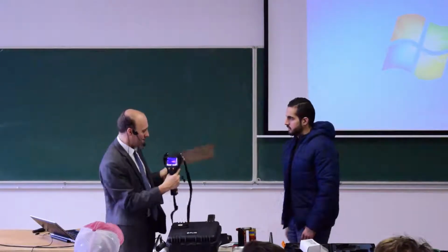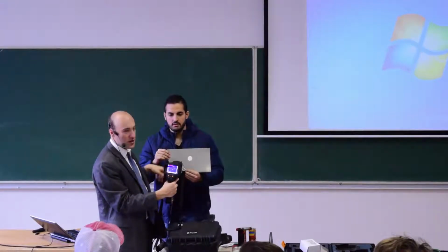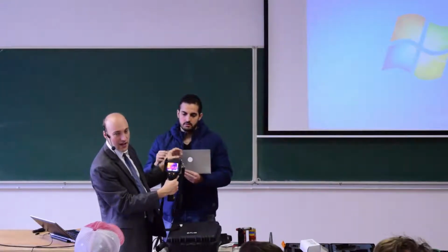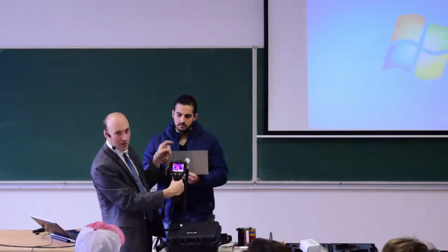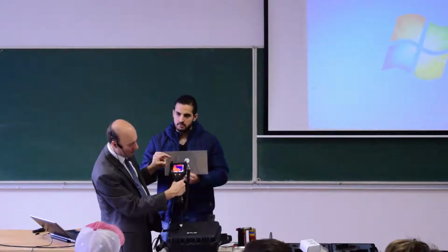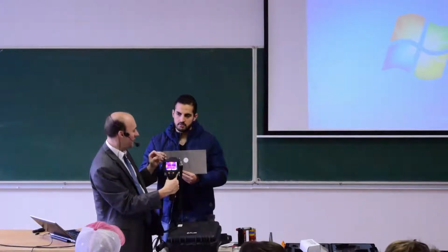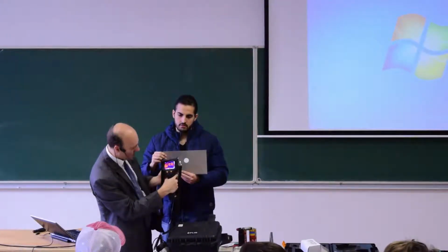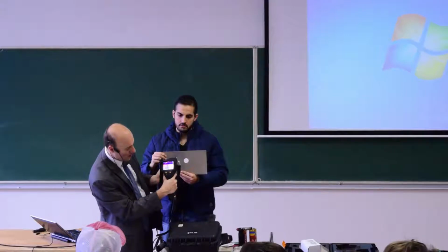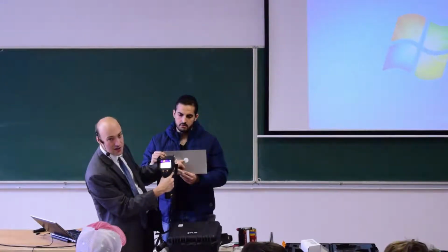Now, stay here, please. If I would like to measure the temperature of this sheet, I cannot do it because I'm getting the reflection from all the ambient objects all around it. And even if I set the emissivity to 0.1, I will not be able to measure the temperature correctly. So the only possibility where I can get the temperature of this sheet is here on this sticker.